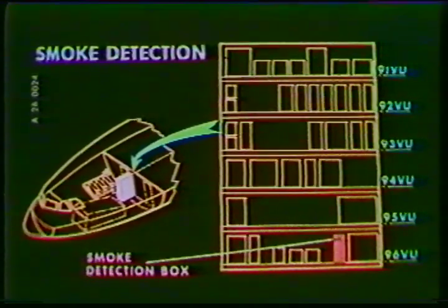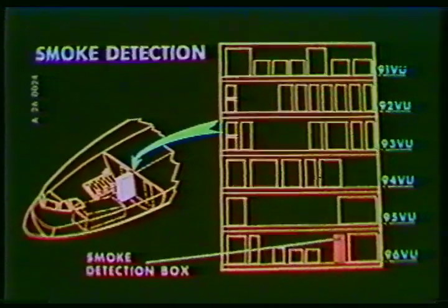It is located in the minimum equipment bay. The box is monitored by a magnetic indicator labeled Detect Fault. It will change from green inline to amber as soon as there is a faulty electronic card. The corresponding amber light illuminates on the front of the electronic box.